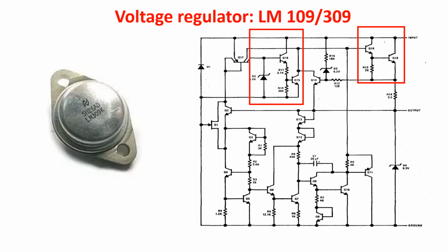When a regulator is protected by current limiting alone, it is necessary to limit the output current to a value substantially lower than is dictated by dissipation under normal operating conditions, to prevent excessive heating when a fault occurs. Thermal limiting provides virtually absolute protection for any overload condition. Hence, the maximum output current under normal operating conditions can be increased. This tends to make up for the fact that an IC has a lower maximum junction temperature than discrete transistors.